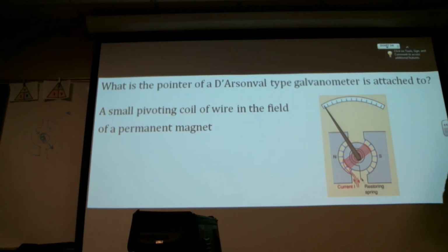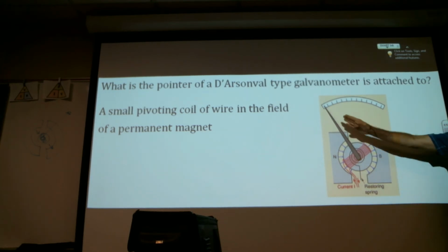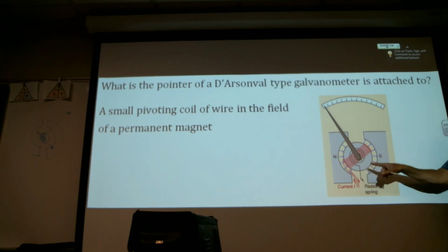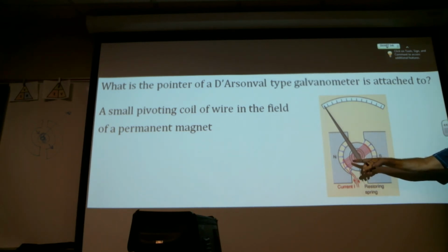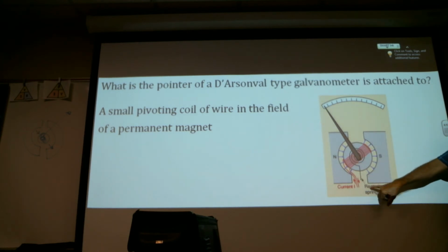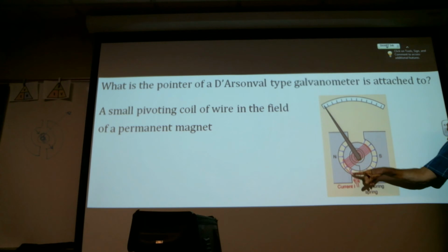I don't care if you're measuring ohms, amps, or volts. If this needle is sitting on full scale, you have the same amount of current going to that coil every single time, because that's what it takes to put pressure against that spring and align with these. So as we make rotary selections, we're fine-tuning what and how that current goes to that electromagnet.